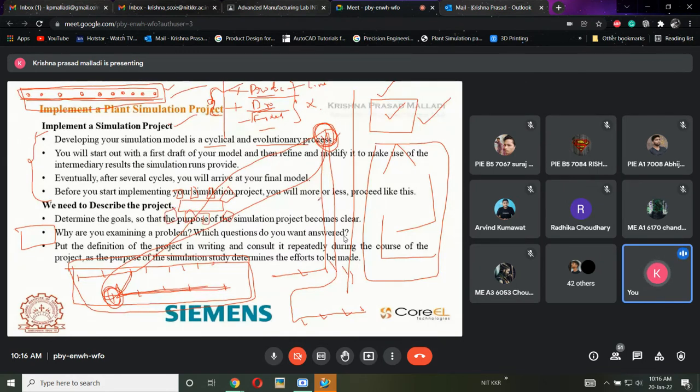The parts are not going to the machine. Why? Because it is not following any product or process layout. Here the part is a vast area, it is larger in shape, so the product will be in this location like this. Simultaneously the machines need to be installed here, so that the part won't be stopped. At the same time the work needs to be performed. That is called a fixed layout.